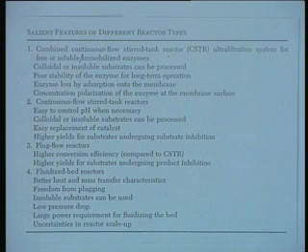Pressure drop is another problem in plug flow reactors, because if we want to eliminate some of the problems associated with internal pore diffusion in the system, the particle size has to be reduced, and reduction of particle size will mean increasing pressure drop across the bed, which ultimately puts an economic barrier in terms of higher energy consumption for feeding the substrate.